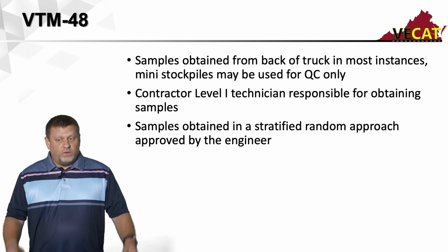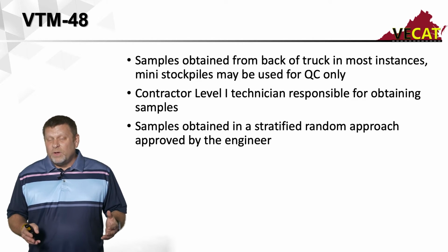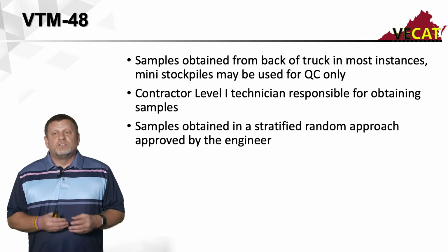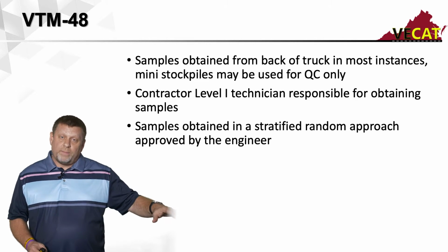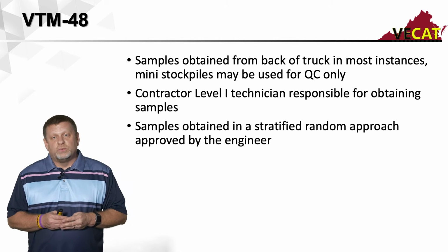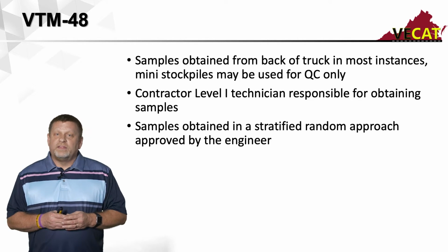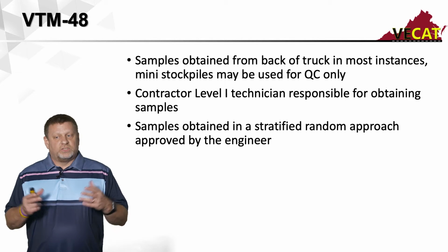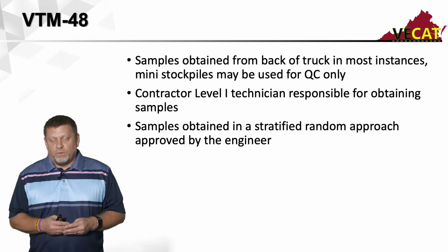I have seen stockpiles done. I don't know if any of you have had a chance to work with the Virginia Transportation Research Council. When they take a sample, they take a much larger sample than you can obtain from the bed of a truck. So they will drop 4 or 5 tons in the bed of a truck, pull over next to the stockpile, dump it out, and have the loader strike it off, just like what you would do with a pile of aggregate. And then they're able to sample straight down from that pile. Since they're getting much larger samples, 20 plus boxes, it gives them a better representative sample.